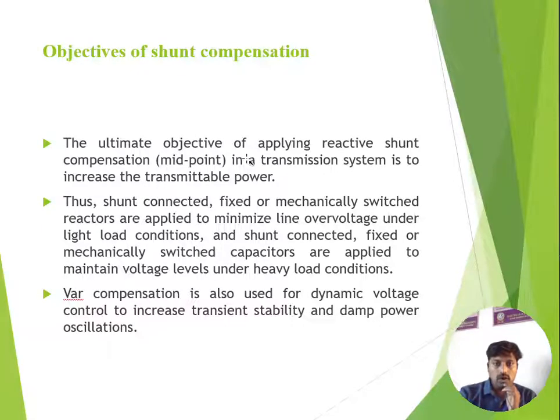So, the objectives of shunt compensators. The ultimate objective of applying reactive shunt compensation in a transmission system is to increase the transmittable power. So always the midpoint compensation. The midpoint compensation is always preferred to improve the active power transfer capability.